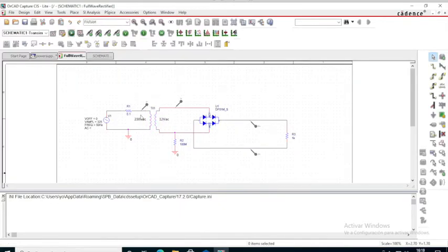And we have test markers only to see the different waves in the input, then the near to 12 volts output of the transformer, which must be around 14-16 volts. Not the RMS, but the peak values. We're talking about peak values now. And then we have the bridge.